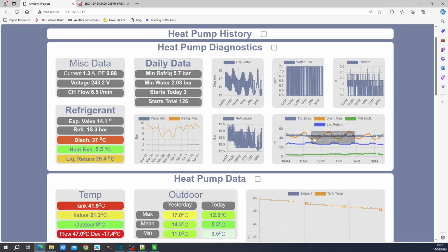And you can see this oscillation in flow temperature going all the way through the day. And that is a much better example of good performance. But with the milder weather, we don't get such good performance in terms of coefficient of performance. But 0.5 amps, that is your minimum. That's your actual minimum. And how to unlock that, I really don't know. That's up to the heat pump.